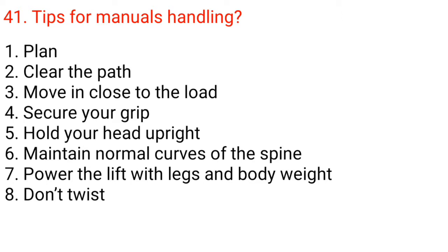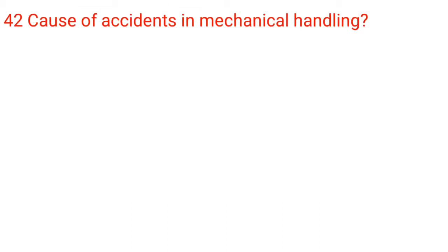1. Plan. 2. Clear the path. 3. Move in close to the load. 4. Secure your grip. 5. Hold your head upright. 6. Maintain normal curves of the spine. 7. Power the lift with legs and body weight. 8. Don't twist. 42. Causes of accidents in mechanical handling.